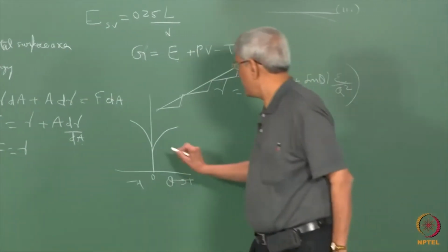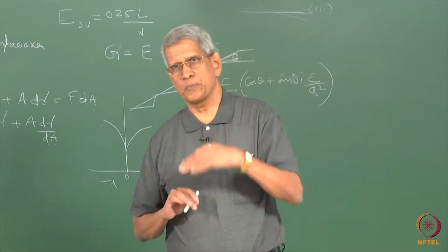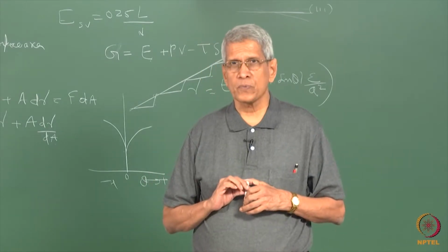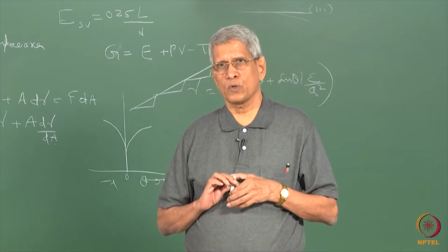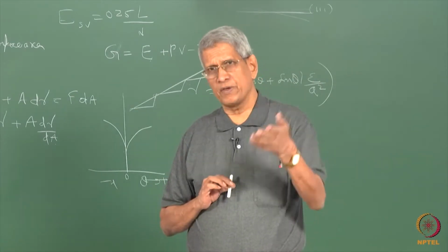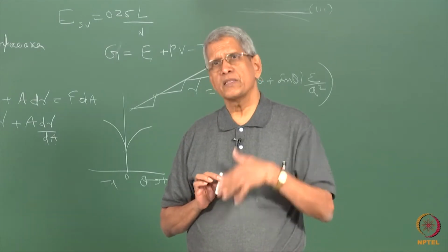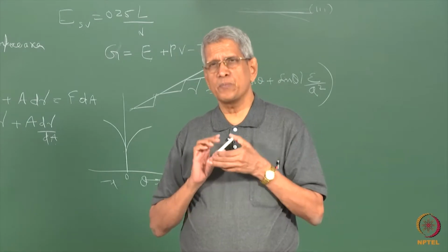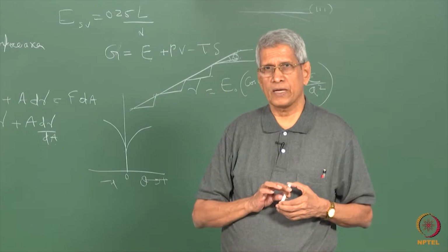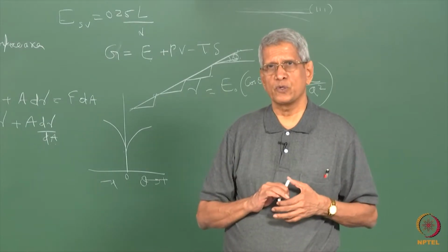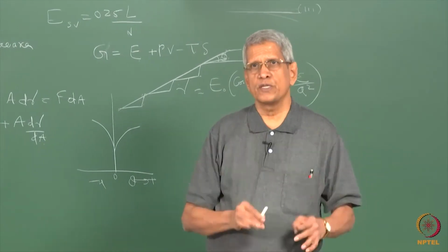So, there is a minimum corresponding to where theta is 0, that means with respect to a low index plane. With respect to FCC, 111 is the closest packed plane. Otherwise we have the 100 plane, and 220 planes are also going to be there. They will have energy which is slightly higher. That means that when we go away from the close packed plane, the energy of the surface is going to increase, right.